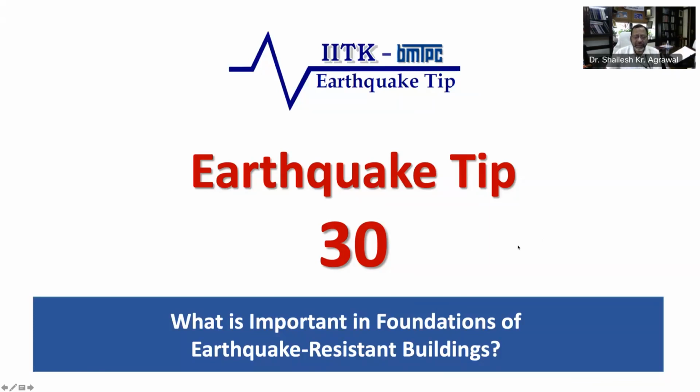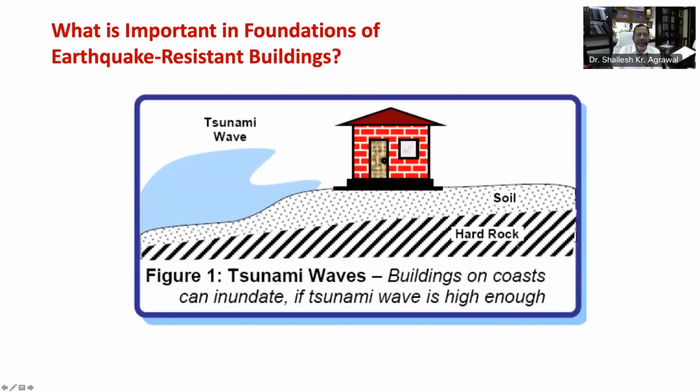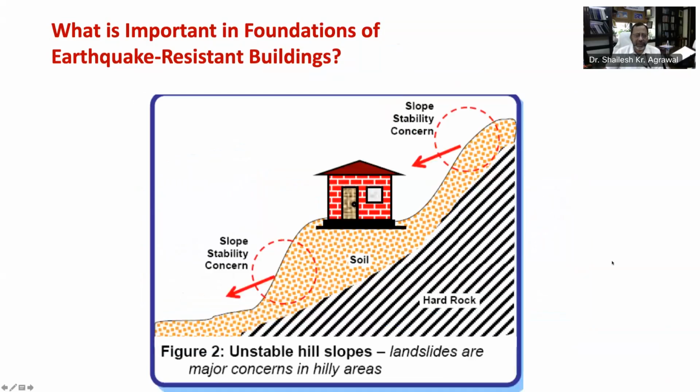The site of the building should be free from any collateral damage due to earthquake related impacts. Therefore, the ideal sites are away from potential fault rupture zone, away from the level of inundation under tsunami waves generated in the adjoining portion by earthquakes, as you can see in this figure 1, beyond the forest and wooded areas with potential fire hazards arising from earthquakes, and free from detrimental earthquake actions on the ground like liquefaction, settlement, and lateral spreading. Now let's look at this figure number 2.